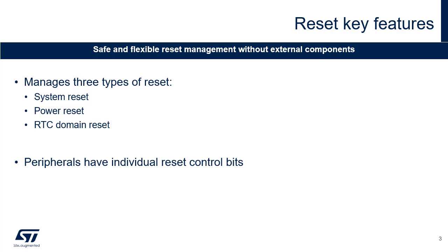Flexible and safe reset management, without needing external components, reduces application costs. The RCC manages 3 types of resets: system reset, power reset, and backup domain reset. Each peripheral also has its own reset control bits.